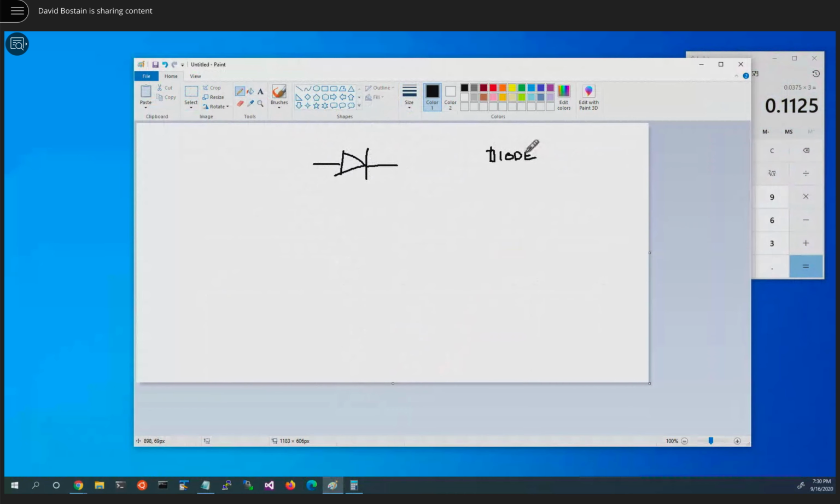A diode is a semiconductor. Semiconductor, S-E-M-I, conductor. And a semiconductor is made out of either silicon or germanium, not geraniums, but germanium, where modern ones today, the ones you'll encounter, are made out of silicon. Silicon, the element, not silicone like body parts are made out of, but silicon. Silicon is a very stable semiconductor where it is not really good at conducting, nor is it good at insulating. It's kind of halfway between.